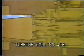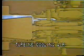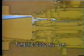Turbine cooling air is routed internally through the engine. Air is bled from the 11th stage of the compressor and the diffuser outlet and directed onto the turbine nozzles for cooling.